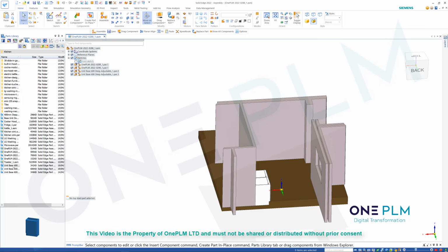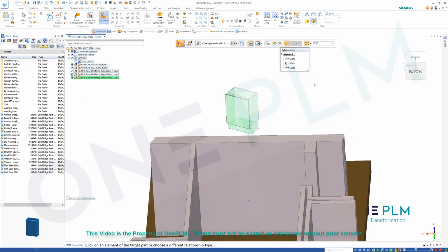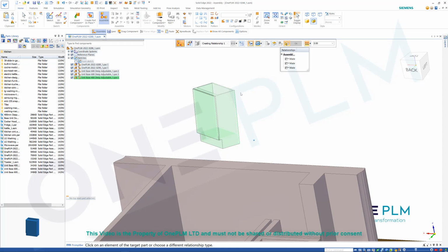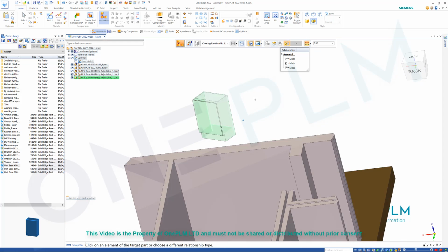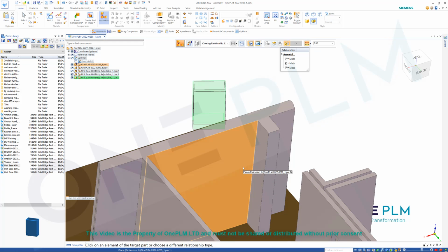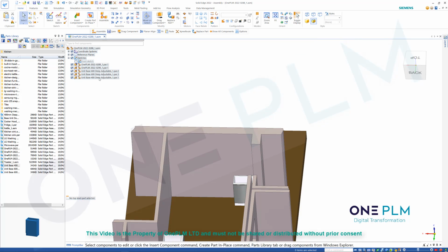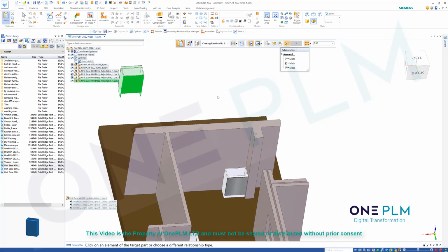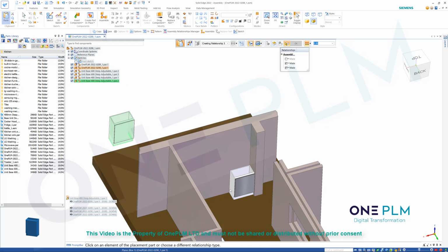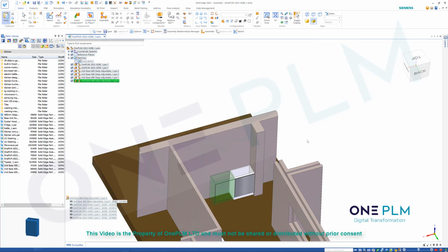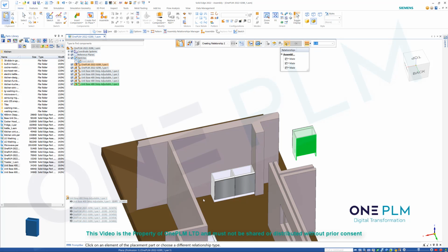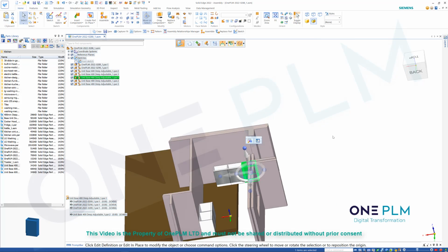So next we're going to pull in this base unit 400 to go on the back wall. What I've done is change that dimension I've just done on that previous one and change that to whatever it will be, 340, 360, etc. And now we can place these on here using similar relationships to what we've got before. Let's just place another couple on there quickly. We know the same process for doing those clicks, and we can now use Control V to paste those in there. So we've got those 3 units on there.